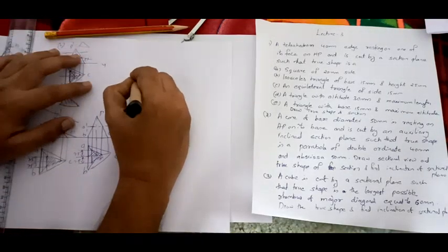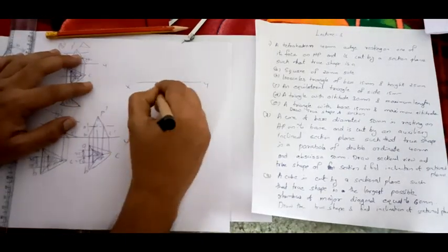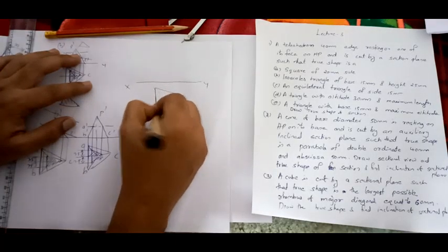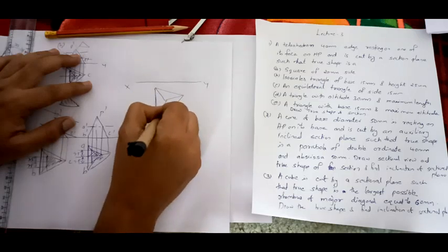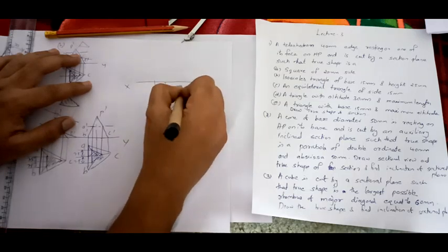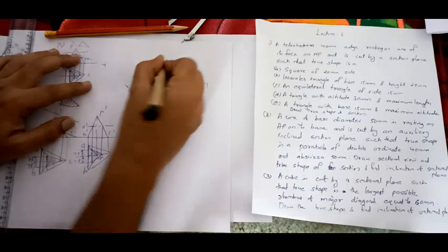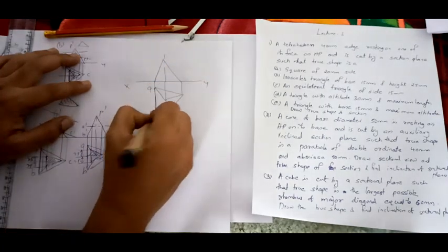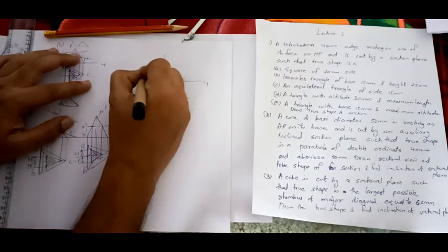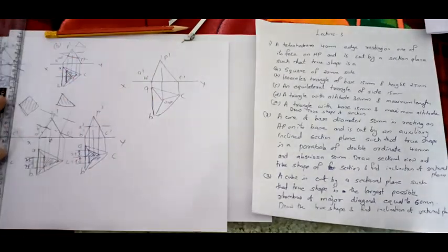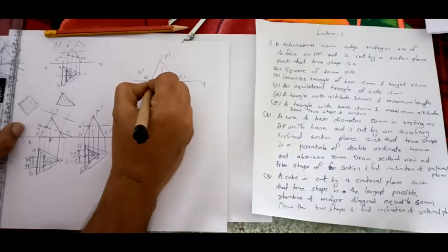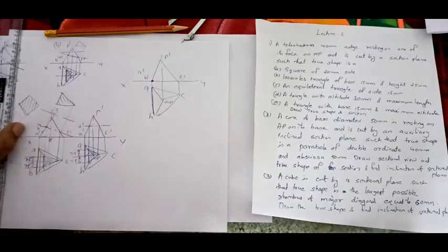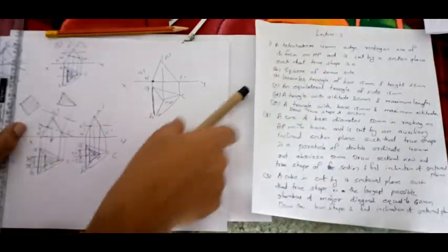It's very simple. Now I'll draw the XY line. This will be your tetrahedron, roughly drawn. Now we will project it. This will be your axis, and you will join here and here. This will be A, B, C, O, P, B dash, A dash, C dash, and P dash. So maximum base means it is cutting here. It should pass through this point. This is your maximum base, and they have given the altitude as 30 mm.